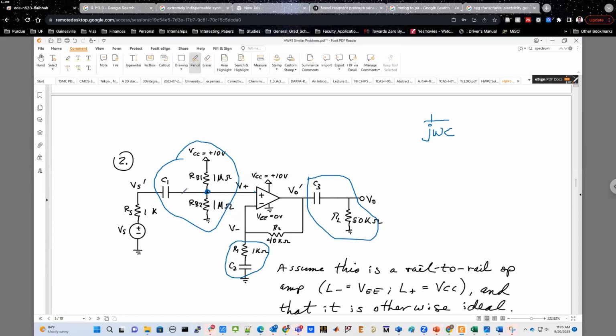Question? So basically, what the capacitor does is isolate the signal. It isolates different parts of the system. So for example, the DC voltage at the left side of the capacitance can be different from the DC voltage on the right side of the capacitance. Like 5 volts. Yeah. So this will be 5 volt. That will not be affected by any DC voltage here. So maybe the DC voltage on this side is 0 volt or 1 volt. That does not matter because you have a capacitance in between.